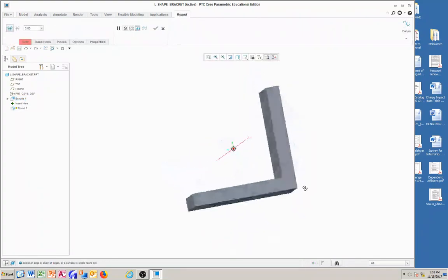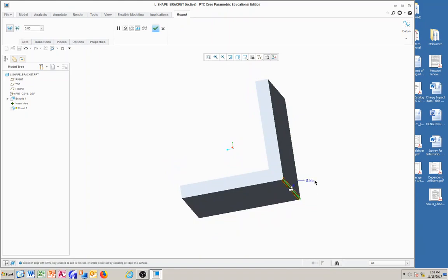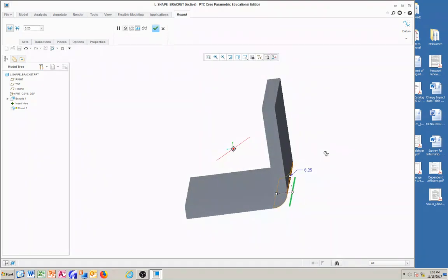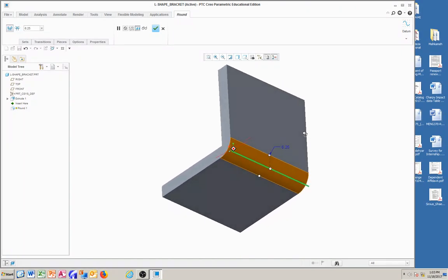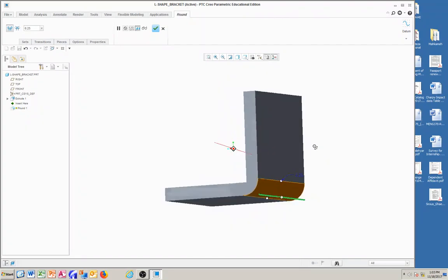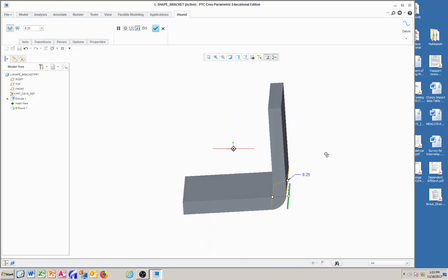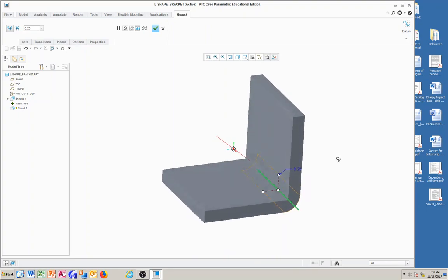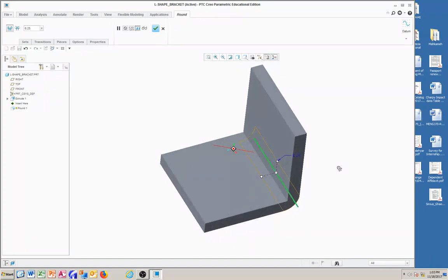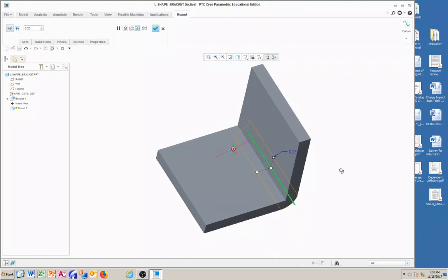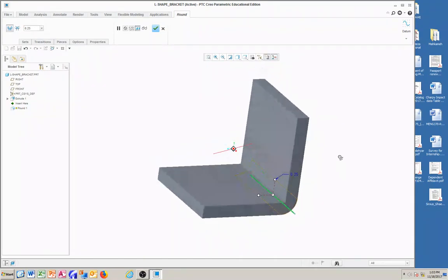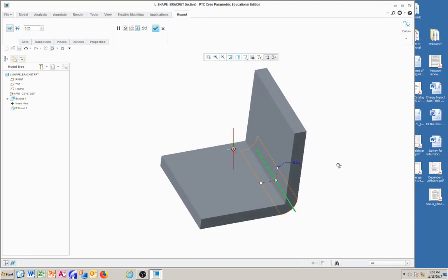The exterior corner is going to have a radius of 6.25. Normally when we put in the fillet radius, it helps the strength of the part. It adds to the strength and toughness of the material if the part is used under cyclic loading, where it would fail due to fatigue. The life of the part will be longer. It's going to be in service for a longer period of time if we add some fillet radii or finished surfaces. That will help in design when you're designing parts.